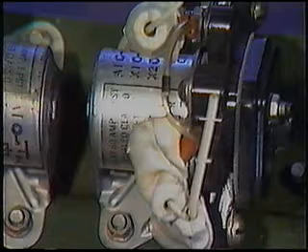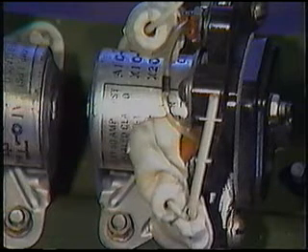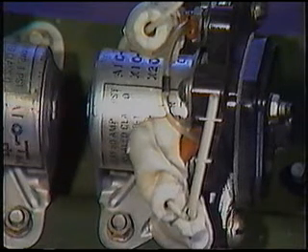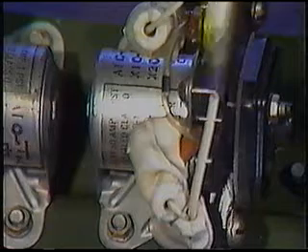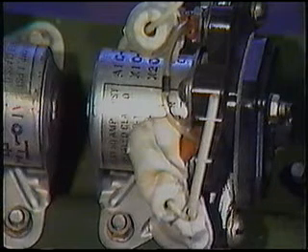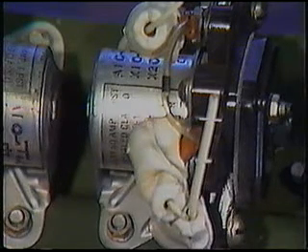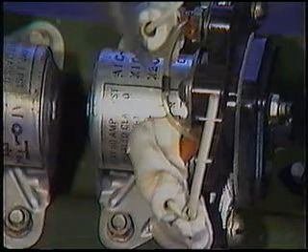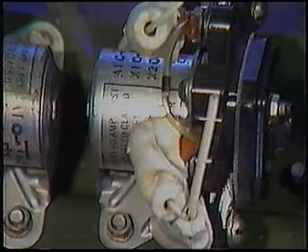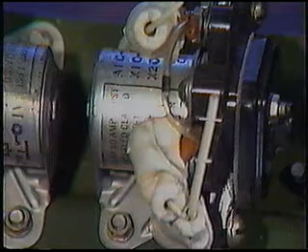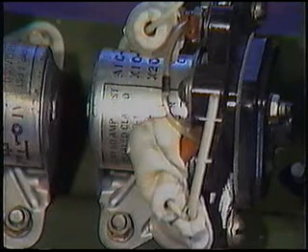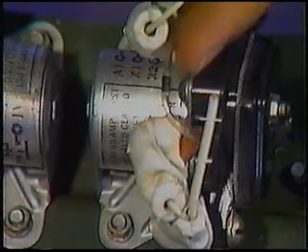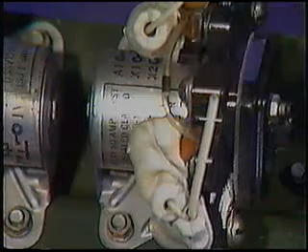Remember, diode installations are used on high spike-producing components, such as large relays or valves. The obvious drawback is that the diode is another component that can fail. Diodes should only be used when all other methods are exhausted. The proper corrective measures for fault-tripping spikes is to ensure proper shielding of signal conductors.